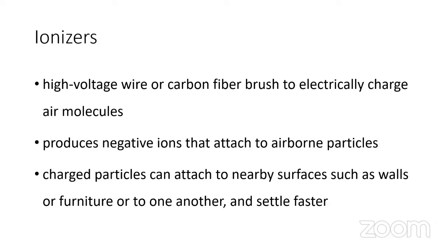So these produce negative ions that attach to airborne particles. Subsequently, the charged particles can attach to nearby surfaces, such as walls or furniture. Such cleaners are available as tabletop portable units, and these ionizers do not typically utilize fans. They just emit the negative ions into the indoor air, and so they typically have very low CADR.